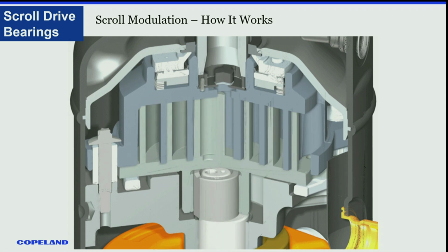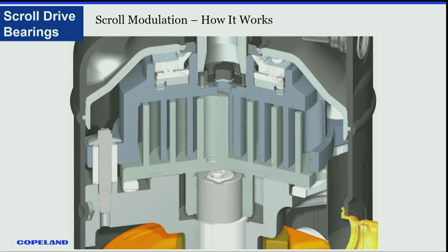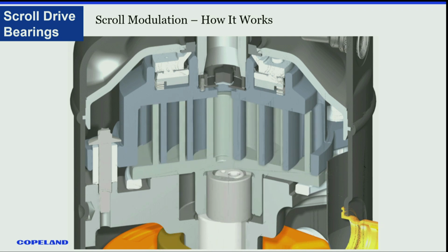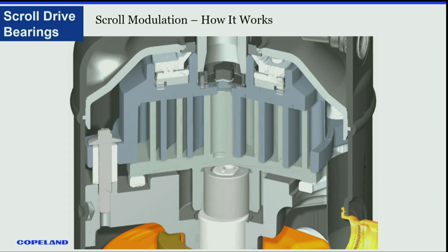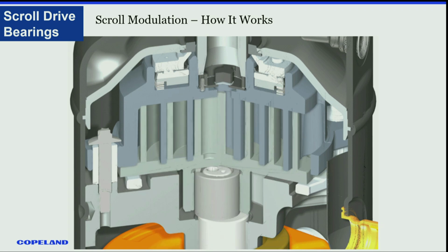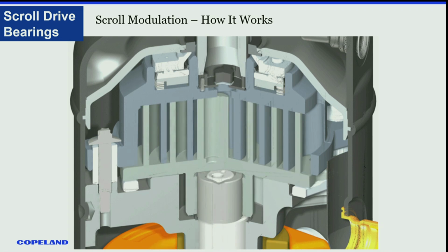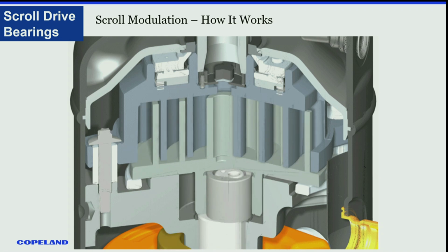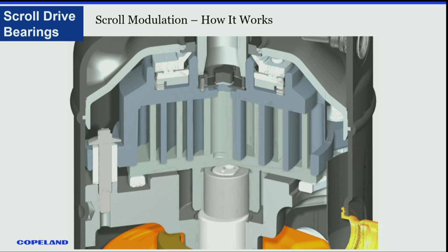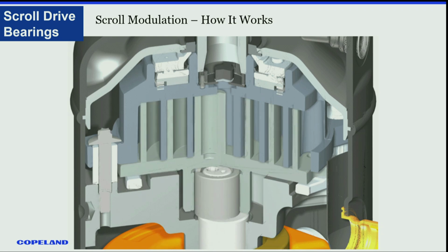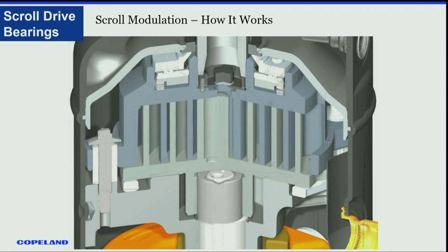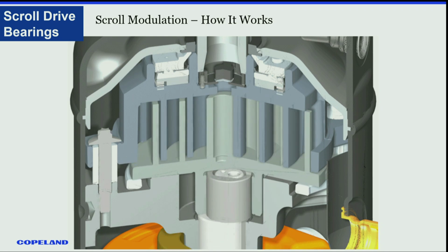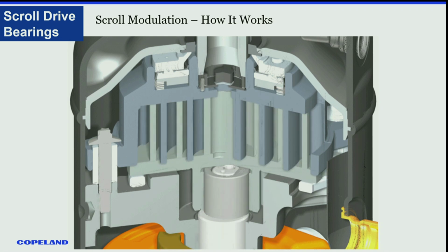Yes? Talking about superheat back at the compressors, how are they managing that? You're maintaining lower superheats down at the cases. Are they just injecting hot gas into it? Or? They have heat exchangers, liquid to suction heat exchangers. There may be, in extreme cases on the medium temp, hot gas dumps as well that are used to manage. There's liquid injection and hot gas dump just to make sure it's not too low or not too high.